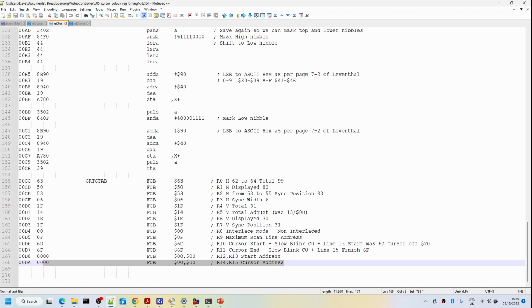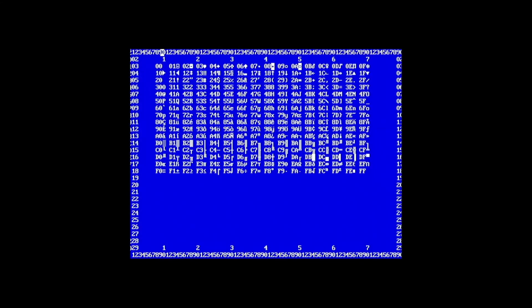So if we now go to the VGA capture, you can now see on the display that we've now got a 16 line full flashing cursor, but it isn't quite in the right place. It's kind of halfway between the characters at the moment. That's what we're going to do with the flip-flops. We're going to fix that. So that just indicates that the cursor is moving, and we can obviously control the size of it.